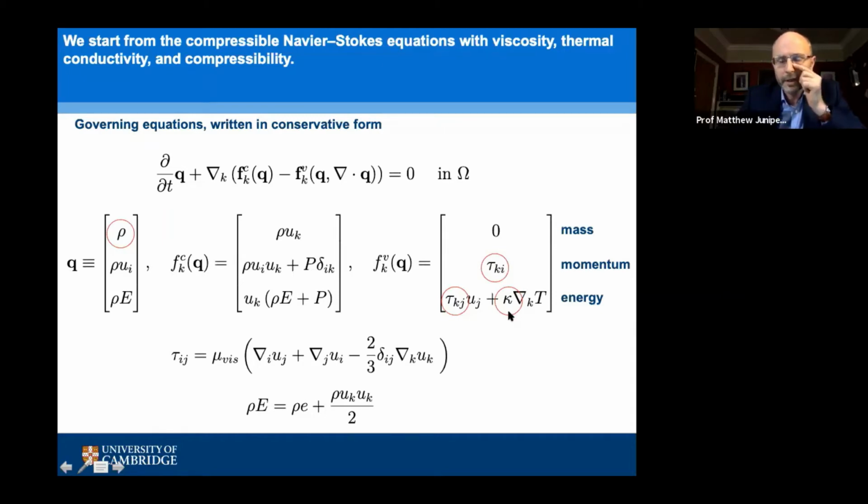And thermal diffusivity is quite important for dissipation of acoustics. I'm in Cambridge today and it's foggy outside, and you'll notice on a foggy day that all the noises get damped. It's harder to hear traffic noise. If someone shouts, you can't hear it so much. And that's because droplets are very good at damping sound. Partly that's to do with the viscous boundary layer around each droplet, but also it's the thermal boundary layer around each droplet. Sound waves are pressure waves, density waves, but also temperature waves.